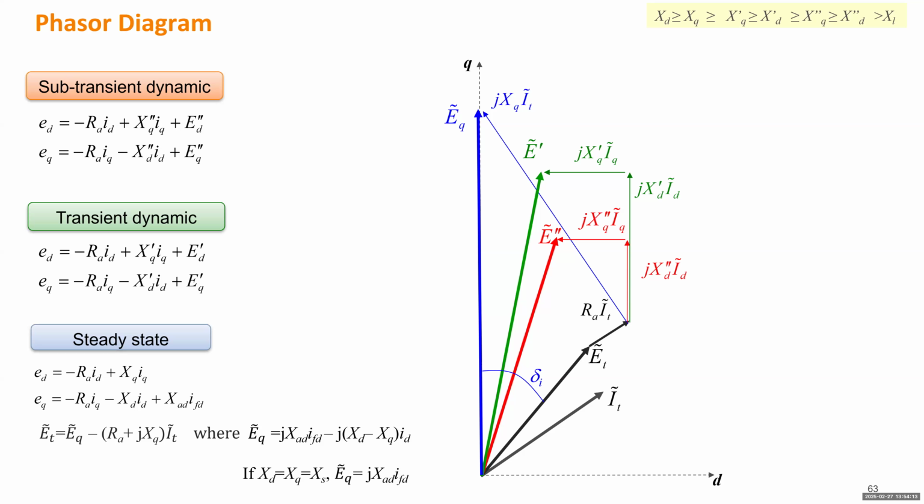To draw another one, because for this case we want to consider a more general case, right? So it's not round rotor. It can be round or cylindrical rotor generator. For round rotor generator, maybe the SD, SQ are not exactly the same. So here we have to consider the current component separately in the D and Q axis. So which means here we need to,